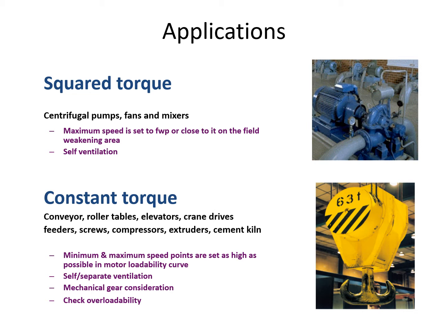the speed range. So what, for example, does having square torque mean? That means if we have torque on the vertical axis here and speed in RPM on the horizontal, then square torque will look like that. Okay. So it's not linear, it's quadratic. So torque will be proportional to the square of n, the square of speed.